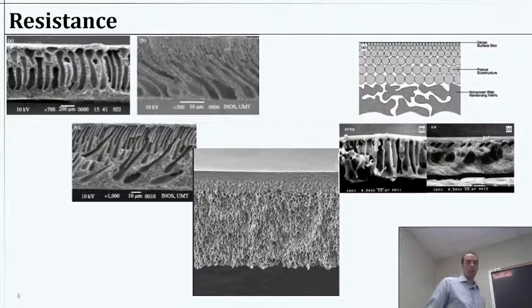And perhaps I should have started here, but when I was talking last time about the support layers, the different membranes, and whether or not you could squash them, this is the type of thing that I'm referring to. In a given membrane here, you'll see that there are these large channels, large spaces. Those would be the support layer. They're large pores. They're effectively trying not to impede any flow. That's trying to let as much water through as possible while providing the pillars or foundation or supporting structure to hold up the selection layer.